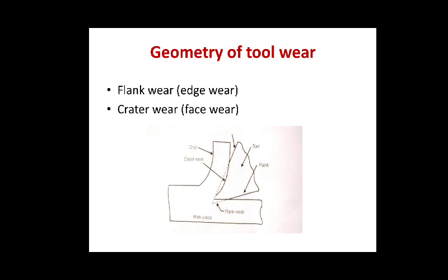Flank wear: the tool slides over the surface of the workpiece and friction is developed, with abrasion and adhesion between workpiece and tool, and a built up edge forms. It starts widening along the clearance face, independent of cutting conditions and tool and workpiece materials, with brittle and discontinuous chips, and increases as speed is increased.